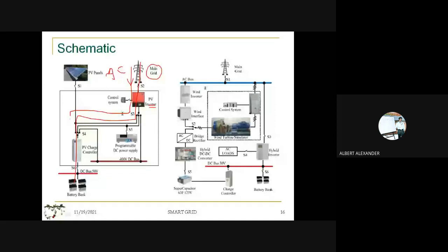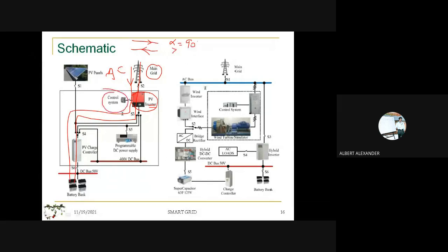So I want to design a power electronic converter which will work as an inverter in the forward direction, and which can work as a rectifier in the reverse direction. How does it work? Whenever you are working with a switching angle alpha from 0 to 90 degrees, it will work as a rectifier. And if it is greater than 90 degrees, it will work as an inverter. So this commanded switching will be governed by the control system. With the help of demand sharing and demand management, it will make things work.